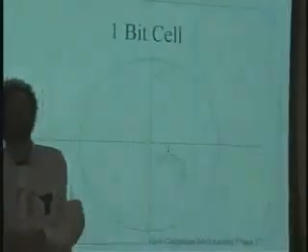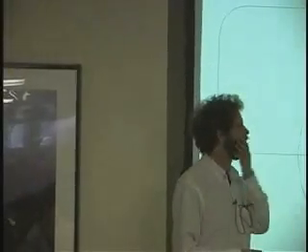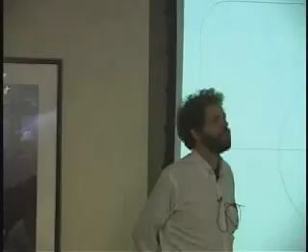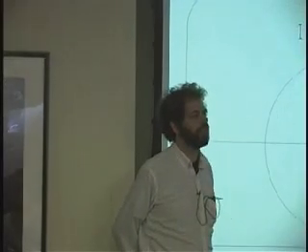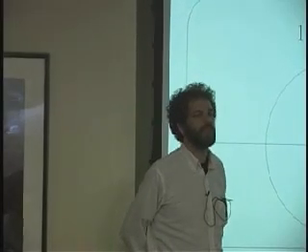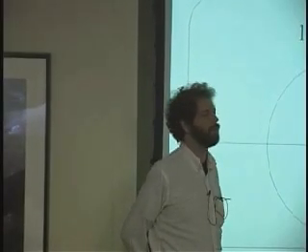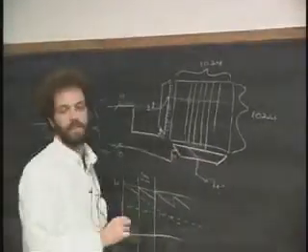What's that? What's that type of RAM? Oh, geez. I think it may be called hidden refresh or automatic refresh, or on-chip refresh. Still SDRAM. It is still DRAM. The S of SDRAM, S is for synchronous, and that refers to some fancier circuits, which we're actually going to go into, that talk about a slightly different structure for here.